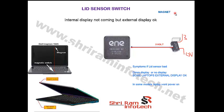If it is toggling like this, 3 to 0, that means this sensor is working. If it is not toggling, there is a problem in the sensor. At that time you have to replace or remove this sensor. What will happen if this sensor is bad? There may be many cases, like in a Compal laptop, your laptop won't turn on at all. If the sensor is shorted, then your laptop will not turn on at all. So at that time also you have to focus on this sensor.